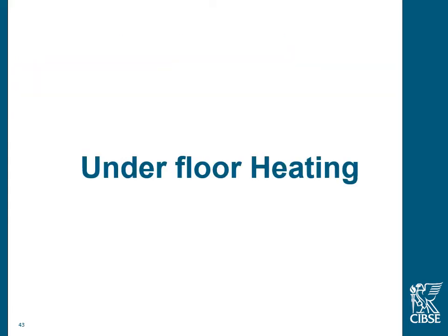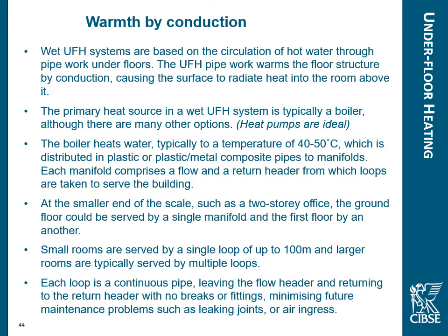Now, if we're going to use a heat pump, one of the better systems is underfloor heating. So wet underfloor heating systems, not to be confused with electric underfloor heating, where we have electrical elements going under the floor, which are quite expensive to run. But wet underfloor tends to take the heat either from the boiler, where running a condensing boiler at a lower temperature can work well, or heat pumps, which are ideal for this situation, because the water tends to be round about 40 degrees, and that's an ideal temperature for a heat pump.